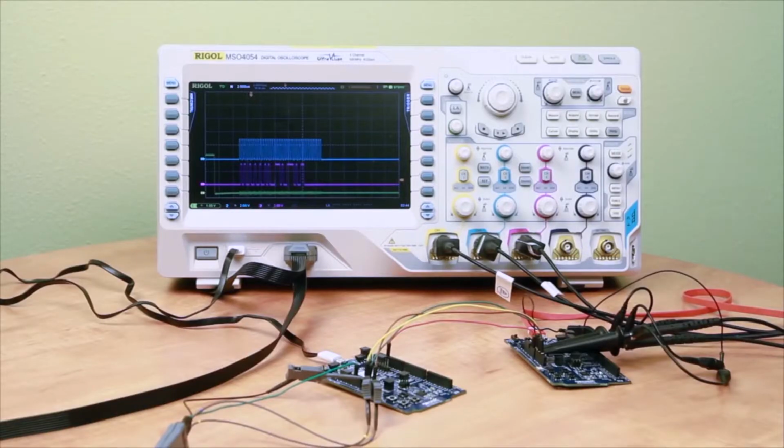All right, here we are with our first serial communication setup, looking at an SPI bus between two IoT development boards. So when you're developing your IoT product, working on an SPI bus, one of the first things you want to be able to do as you debug your code is monitor that bus, both physically and for the code it's being sent. So here we've hooked up our oscilloscope, looking at the chip select, clock, and data lines.